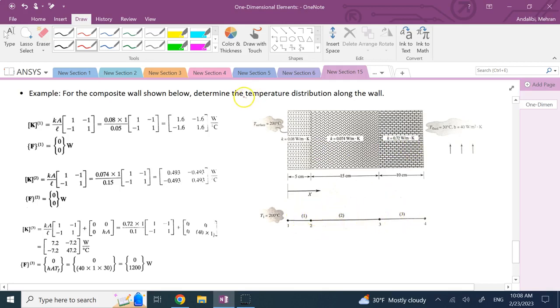Of course, when it says the temperature distribution along the wall, what we want here is to go from this number to this, to this, to this using 3 lines. So you would get something like this, for example, right? You get 3 pieces of line. If you want to capture the real dynamics of everything, you better use more elements per portion of the wall, or at least use higher order elements. But here we go with the simplest FEA analysis possible. The minimal number of elements, 3, and the simplest type of element, line. Okay, linear elements.